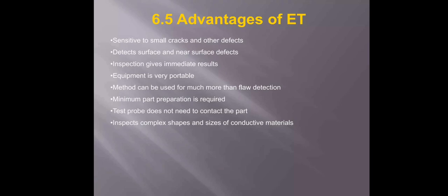Limitations of eddy current testing: only conductive materials can be inspected. Surface must be accessible to the probe. Skill and training required is more extensive than other techniques. Surface finish and roughness may interfere. Reference standards needed for setup. Depth of penetration is limited. Flaws such as delaminations that lie parallel to the probe's coil winding and probe's scan direction are undetectable.